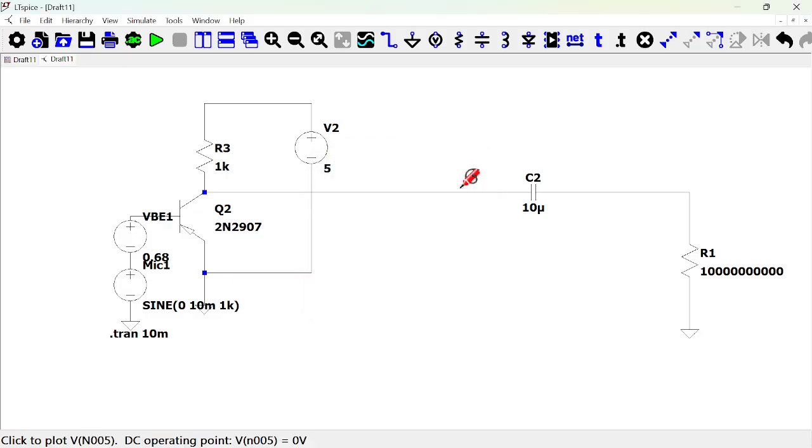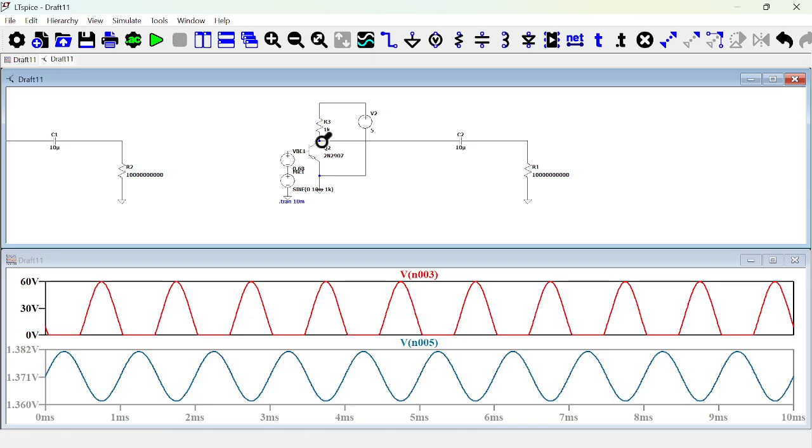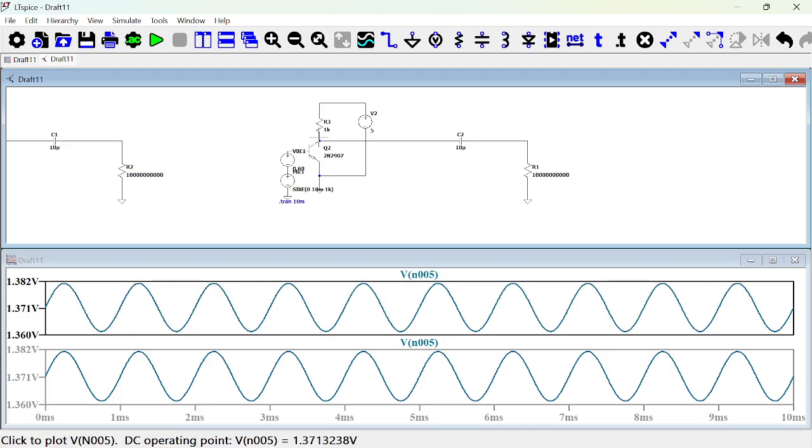Okay, so the condition is that for the transistor to operate as an amplifier, the base collector junction should be reverse biased and the base emitter junction should be forward biased. So assuming there's a lot of things wrong with the circuit, when we do this and we run, what are we going to get? Because this is what we'd have done for the NPN. Any of them works, and I want to see the voltage here at the output.